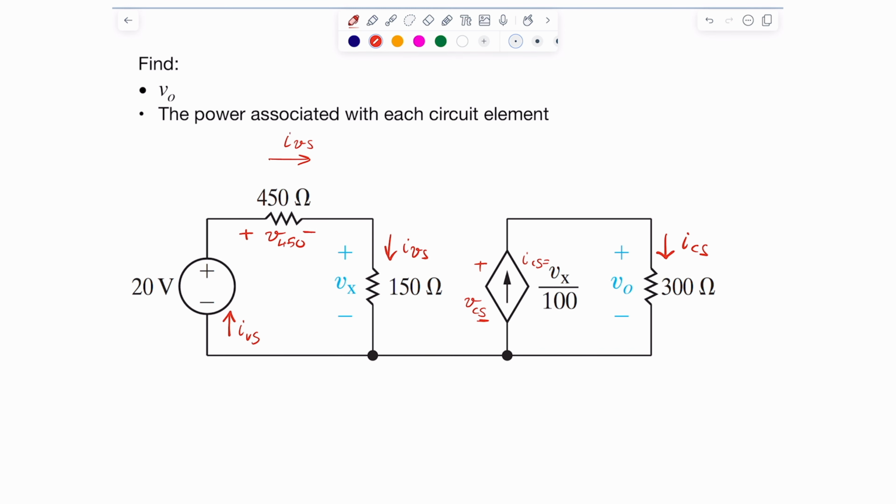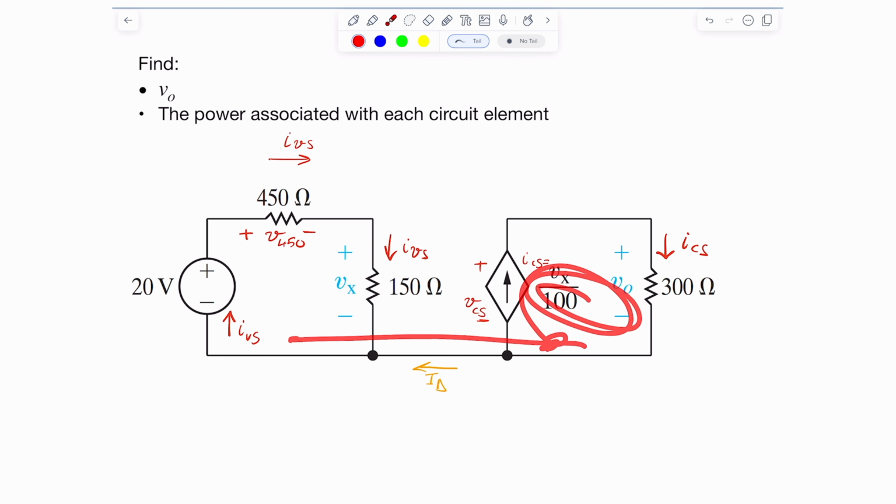All right. So the voltage here is identified already. So we identified everything except one that I left out on purpose, which is the one here, I delta. And I'm going to show you that this particular I delta is pretty much 0. The reason why is if there's a current coming from this part of the circuit to this part of the circuit, there must be a way for it to come back. And since there's none, there's no current flowing through this wire.